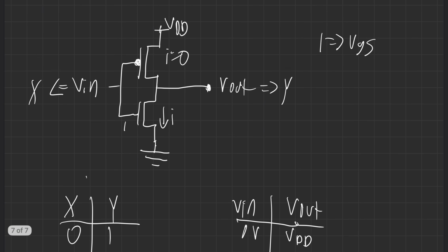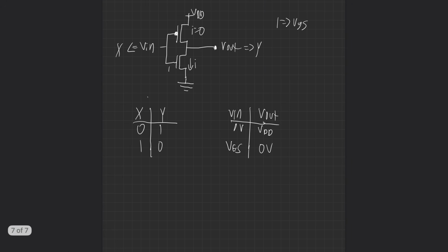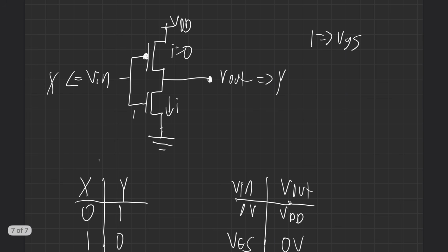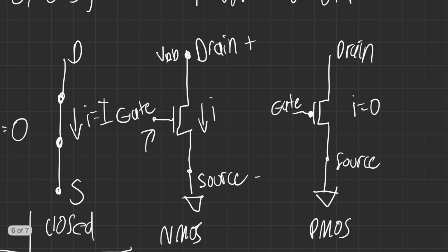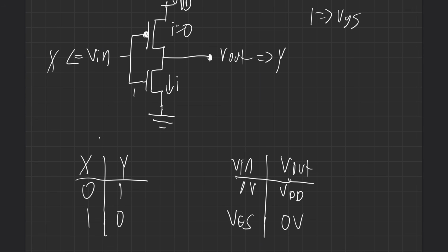So anyway, this is like an inverter circuit. I explained to you PMOS, NMOS, and then ultimately CMOS, how to use a PMOS and NMOS in a circuit to actually keep chaining logic, which is we're using voltages to determine that. So maybe that's the other side I want to say, that with this, you can't really use logic off this. You could, but this is the CMOS. There's a lot of advantages, but maybe the biggest one is that there's a straightforward way to chain it.